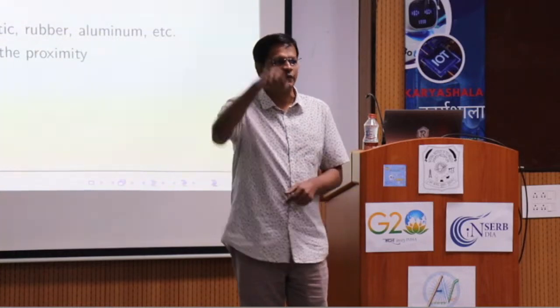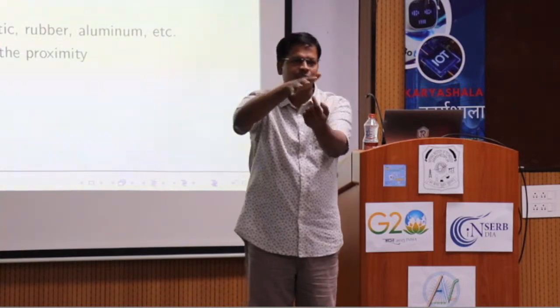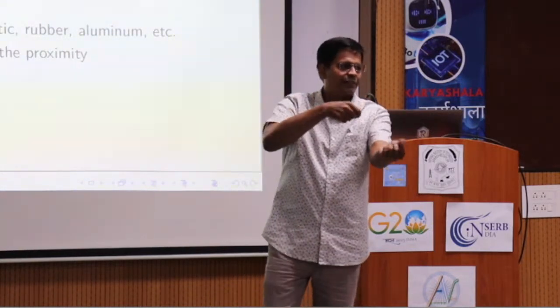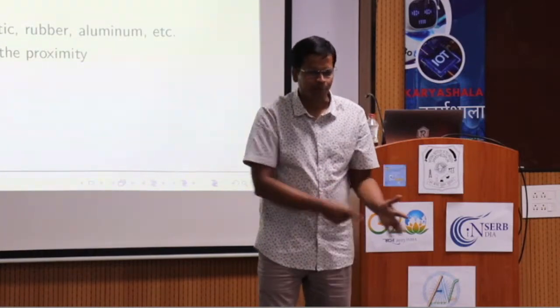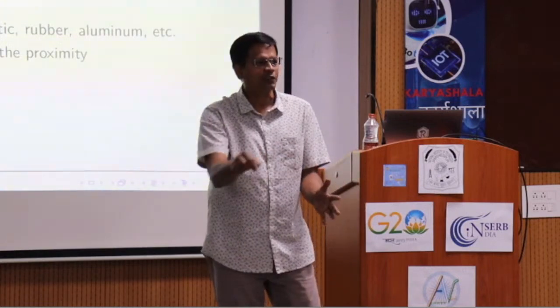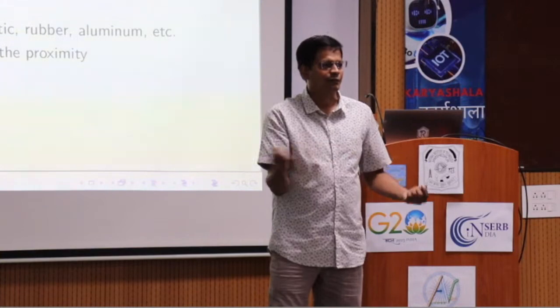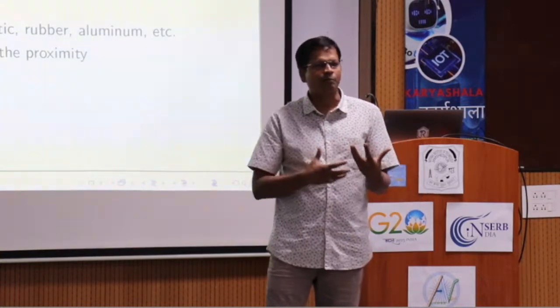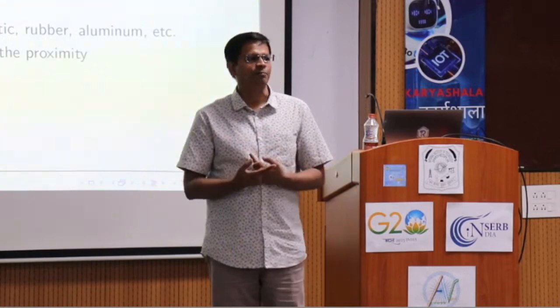Then comes your end effector frame, that is at the tip of your flange somewhere. Tool flange is there, where it is actually doing some job. You have object frame, you have base frame, that is the workspace frame on which robot is working. So you have different frames which are kinematically linked. You have to have complete knowledge of frames as well as relation between them.